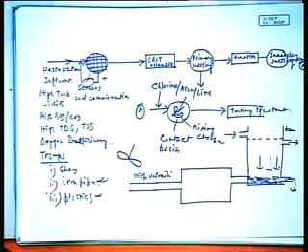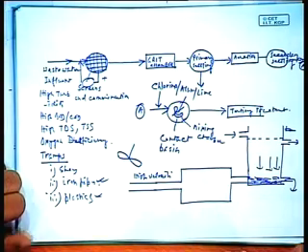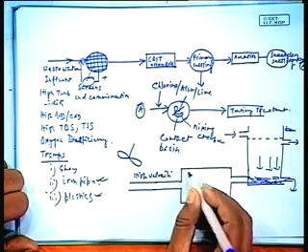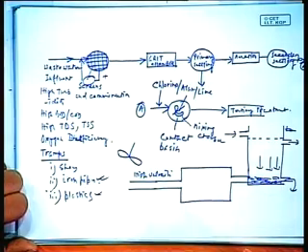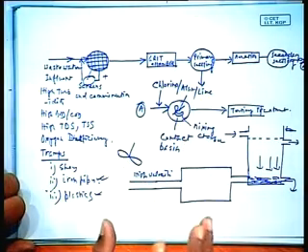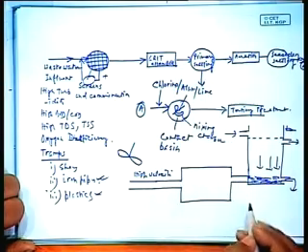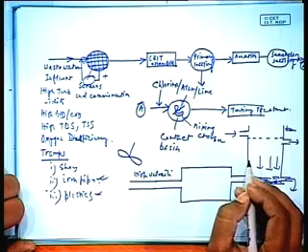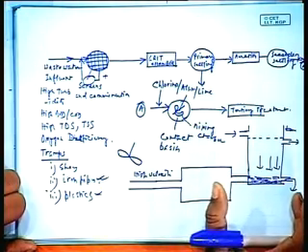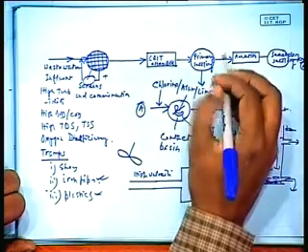Till this time we have not seen any reactants being added to the water. We have not added anything so far. We are just trying to physically remove things from the water. This will be followed by the grit chamber, and there may be another primary settling tank where even smaller particles would be allowed to settle.